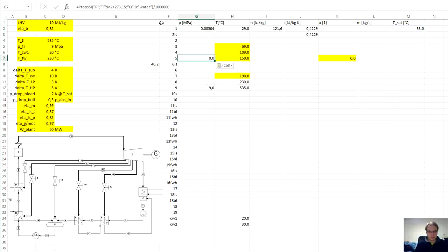So we can leave this temperature, just saturated temperature is the same as the temperature itself, and quality is specified here. We can see that the pressure is a little bit less than 5 bars, about 5 atmospheres. And this is the pressure that, assuming no pressure drops in the water line, is the same everywhere downstream down to the pump.